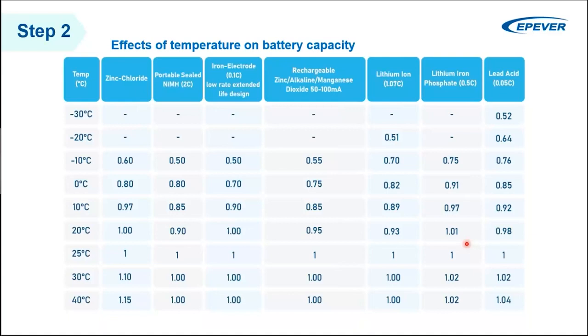The life cycle of the battery decreases over time if you use it at high temperatures. It's also found that when the battery is charged at higher temperatures, the life cycle degradation is more significant over time. So it's really a big trade-off between the life cycle and the capacity that you're getting while you're using the system. The cold weather also affects the capacity.